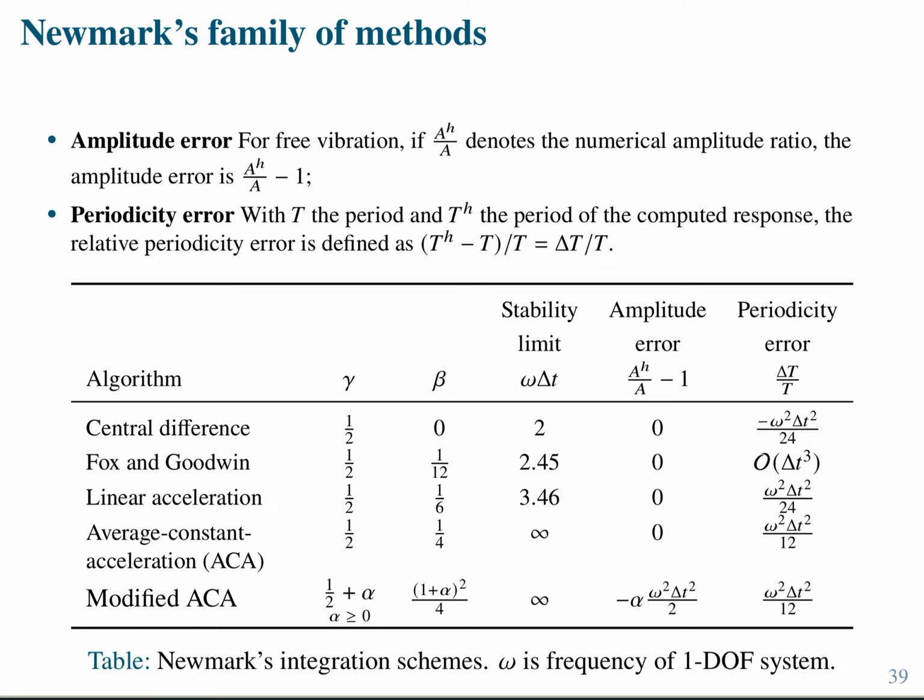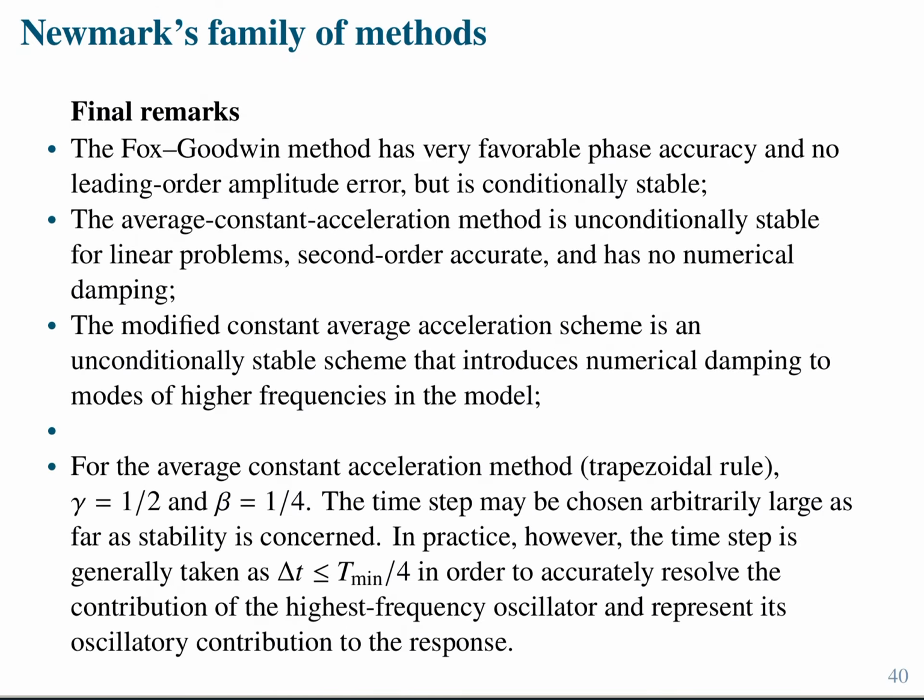In reality, we want to see the dynamic response with enough accuracy so that if you have high frequencies, you don't jump from here to there, losing all that information, right? So in a way, you really want to choose a time step that allows you to obtain the solution at the level of precision of your highest frequency in your response, okay? Or maybe not. Maybe you just want to get rid of all that high frequency content and obtain whatever the main response is. Yeah, you tell me?